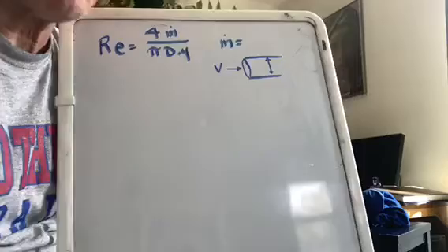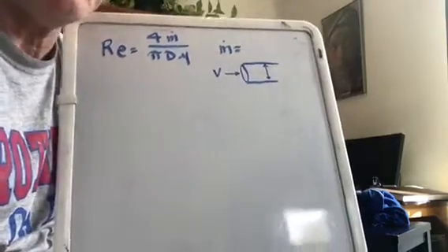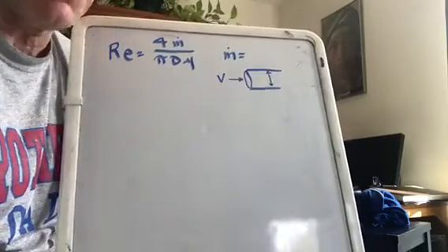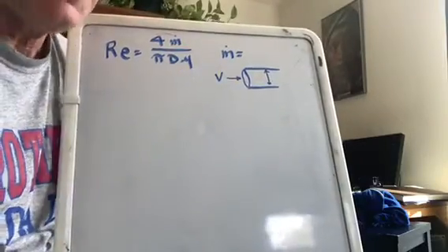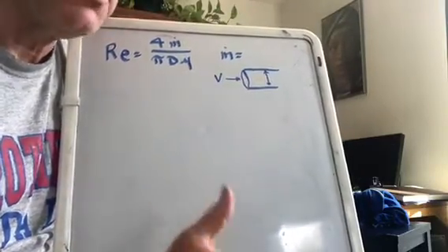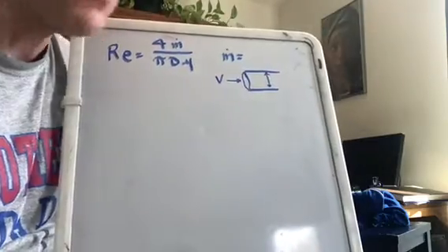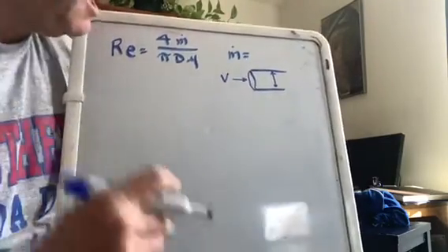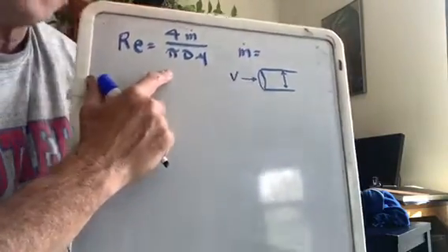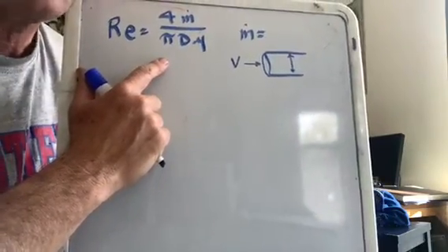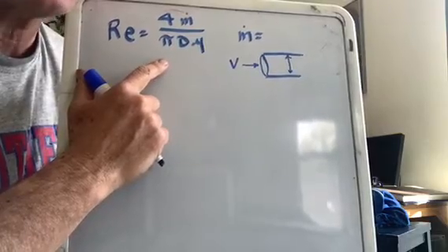All right, so what we're working towards is understanding efficiency of flat plate collectors, and a huge part of it is whether the flow that we get through the tubing is turbulent or not, and you guys can do that calculation. I'd like to do just a little bit more where we figure out the H value, but to finish off for today, let's get that other version of the Reynolds number flow up there. So this is a good, valid form of the Reynolds number. To me, it conveys a lot about tube flow.